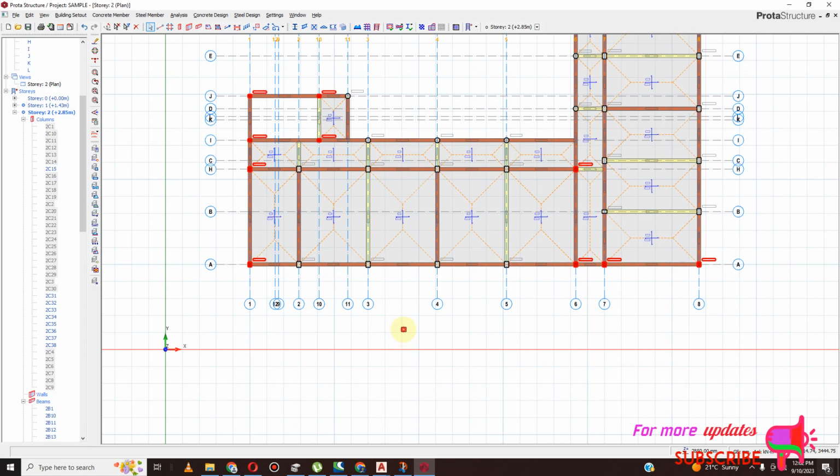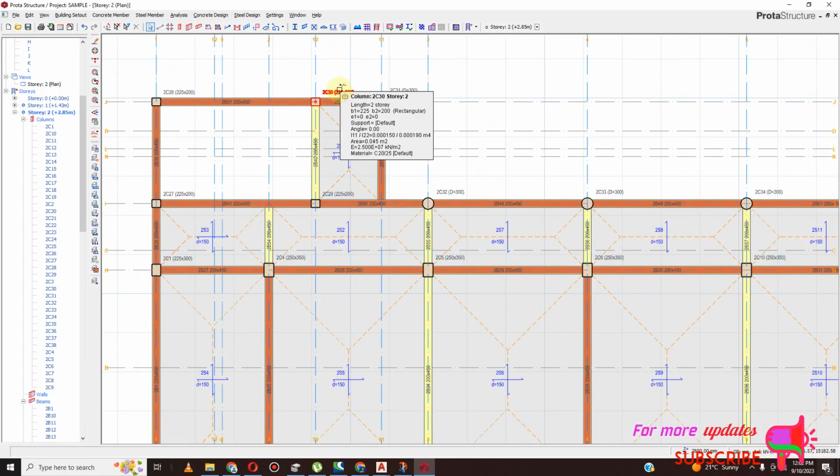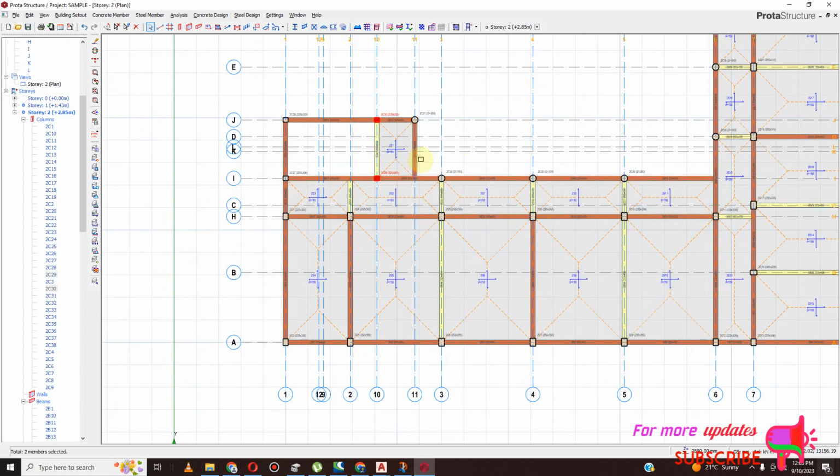The other important point is, you should know that the stairs columns, which are going to hold the water tank, should be bigger than the other columns. You should have that in mind when you are modeling. They should always be bigger than the others, because the water tank is very important and very critical. So we need to design to make sure that the columns are stable.